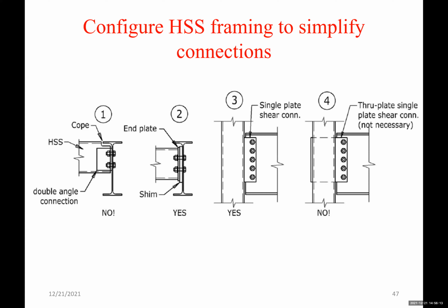Configure HSS framing to simplify connections. So do not cope HSS sections. For example, in the first case, this is not preferred. Cutting HSS sections will release some residual stresses in the member as a closed shape. So this is not a preferred option.